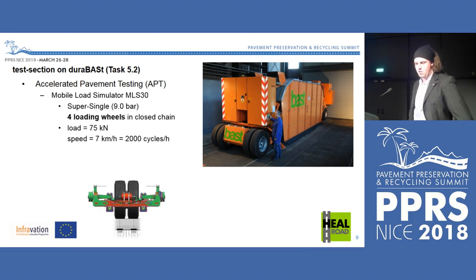Because of the goal of this research project to get stone loss, that was the only thing we could realize in this small and short period of time. That was our idea. We decided to lift up the load to 75 kilonewtons. The standard load in Germany, compared to our design guide, is 50 kilonewtons. And we had a speed of 2,000 loading cycles per hour.